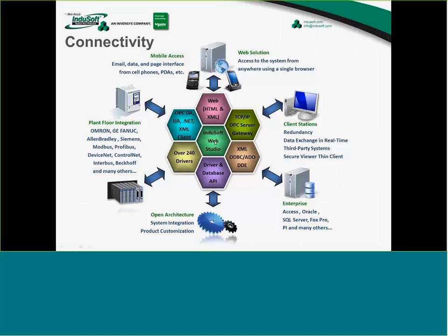So reading information out of one PLC and then writing it to another is something really neat and easy to do. We also support OPC, as I mentioned, as a client: either OPC DA, OPC UA, OPC.NET, and OPC XML. And when you use those tags in an OPC client communicating to a third-party OPC server, that OPC does not count against your driver count.